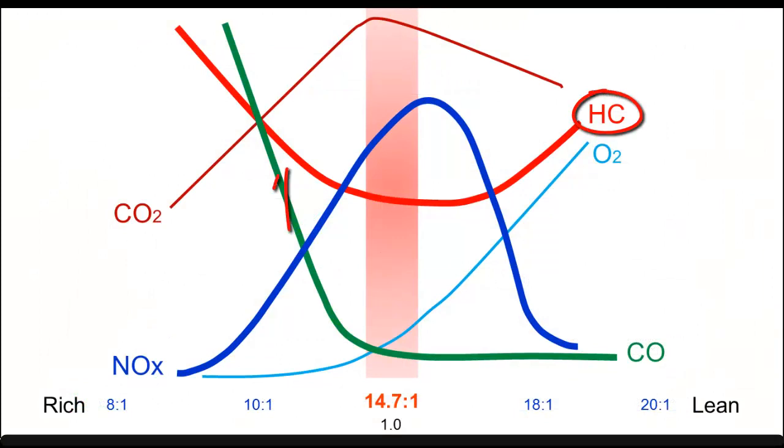Hydrocarbons up at 320 parts per million. Carbon monoxide up at 8.72%. NOx remains low at 3 parts per million.